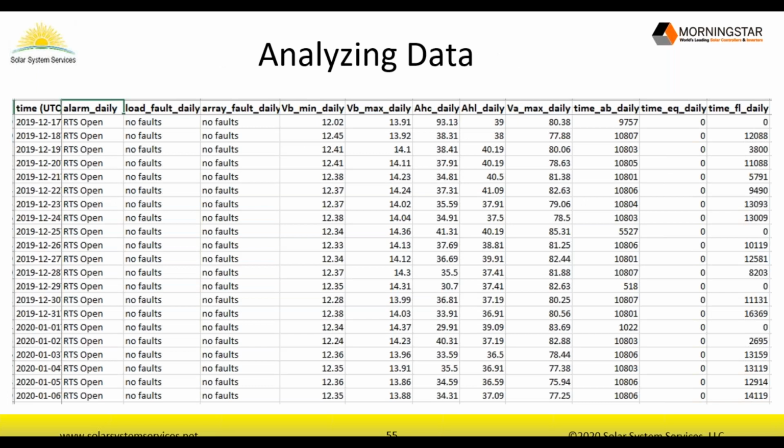This is an actual log file from a site, and those dates are correct and accurate. This came from a client of mine that allowed me to use this data with their permission. This site is in California. It's actually used for sign lighting, so they're lighting up a sign, and it's set from dusk to dawn. So actually we didn't use the custom settings. We didn't need to. We just used that standard dip switch 1 to set it up for that. It's also a 12-volt system.